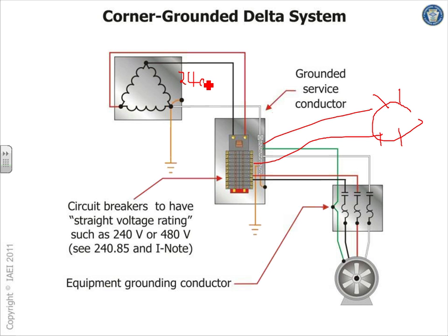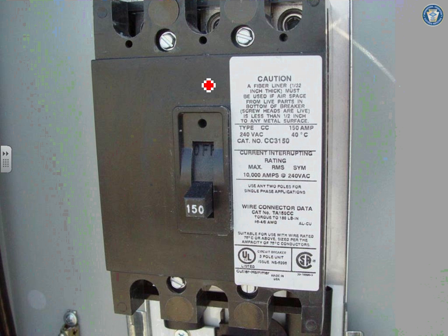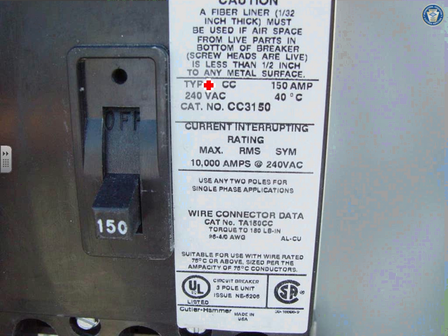If you have a delta system, guys, your circuit breakers also have to be rated for it; they call them delta circuit breakers. And somewhere here it says rated for. You cannot use a slash voltage rating for it, basically. So here you go, right here the type is 240. So 240 line to line or 240 line to ground. It doesn't matter here.